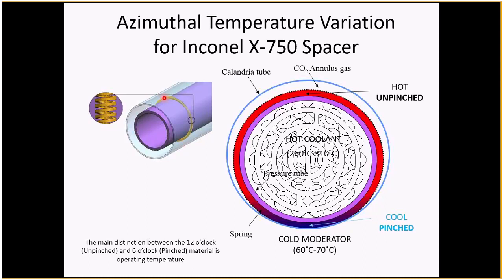And it is a spring. It's a garter spring because it has to roll. It has to allow free passage of this tube inside the concentric tube, which is the calandria tube. So these tubes have to move one with respect to the other. And the best solution to avoid galling or anything else that would interfere with this free movement was to make this separator a spring.